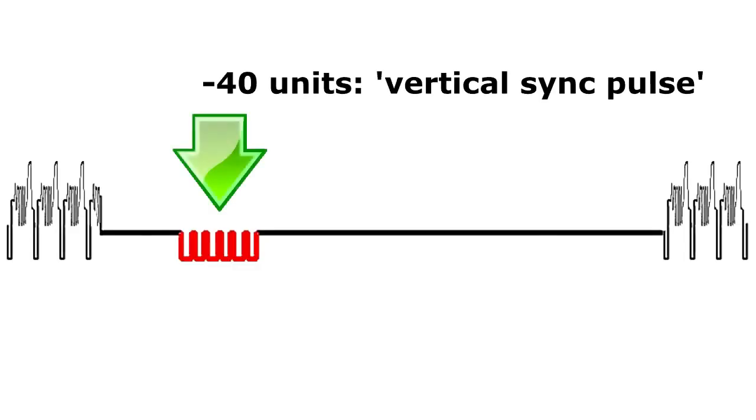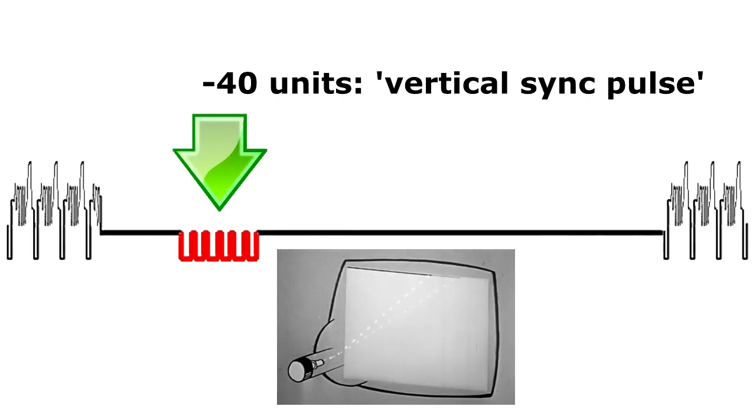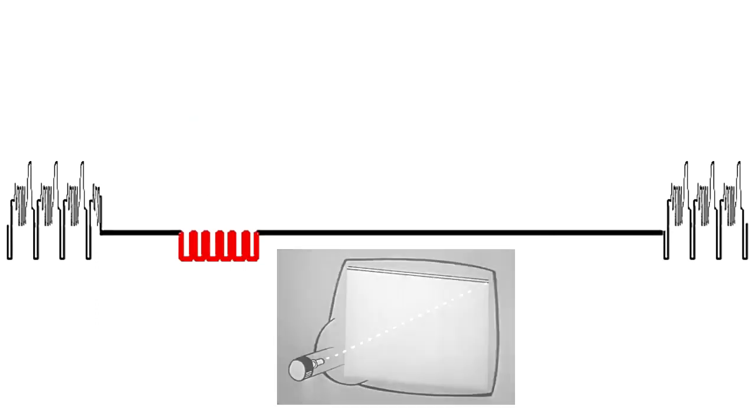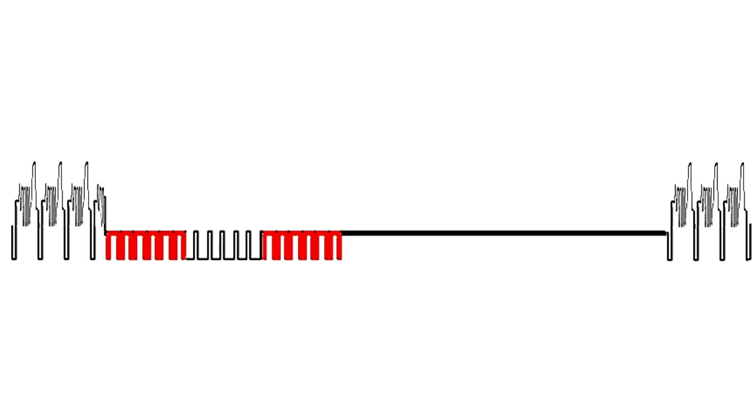15,750 equals 31,500 Hz. Groups of equalizing pulses just before and after V alignment are used to improve vertical alignment in even and odd fields. The half-line serrations in the vertical alignment pulse also have a frequency of 31,500 Hz. In fact, the pulses for equalization and vertical serrations are similar pulses but with opposite polarities.